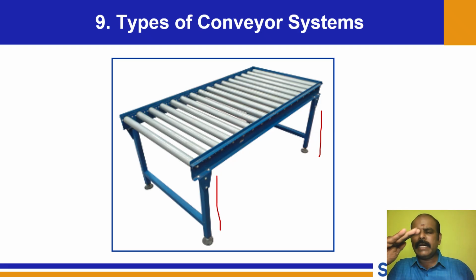A small taper, a small difference in height will easily solve the purpose. These rollers are nicely free to roll, so at either end we want, it can easily roll onto it. So now we'll analyze the advantage with respect to the earlier one. The earlier one was power driven. There were several idlers, and here nothing. It's very simple. The only thing is you have the difference in height with respect to the platform. Therefore, we get the requisite amount of taper. Therefore, it is a free-fall nature.